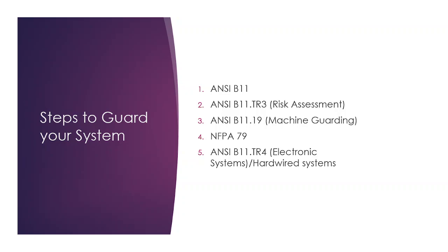You also have the option of using a hardwired system rather than using some type of safety rated PLC or safety rated controller. The traditional way is we always would have done a hardwired system with the physical safety relay that would monitor the circuit, rather than using a physical safety PLC that's configurable. We're switching more and more to the configurable systems, not necessarily because of reliability, though they are well into the reliability standard side of it, but because they're becoming easier to troubleshoot when you have multiple systems connected to those. So definitely something to consider for your particular application.